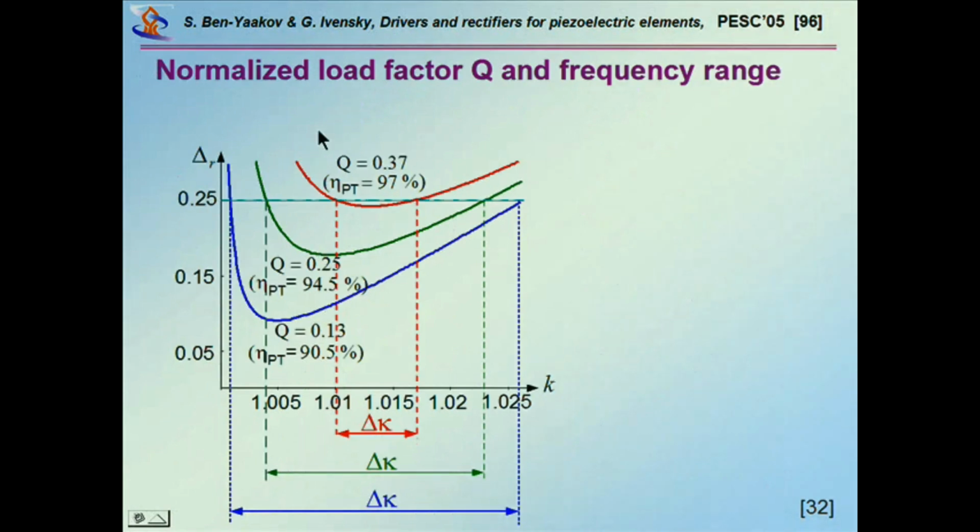Well, as I've said, we did some work, and there is the reference here, 32, and it turns out that it's pretty much limited what you can do. It is possible, but it is limited. What is shown here is the quarter of a period needed for self-commutation. That is, in order to have self-commutation, the voltage should increase within a quarter of a cycle. Otherwise, it sort of continues. Okay, and so all the curves below this range are providing soft switching.